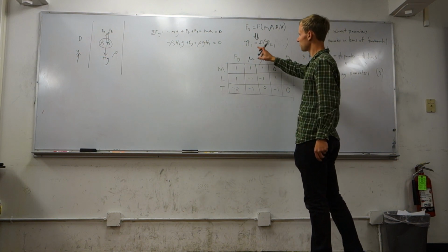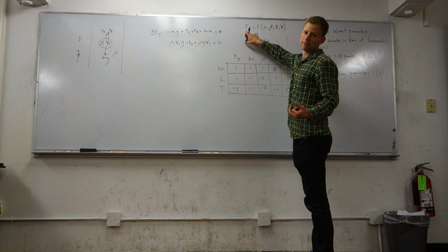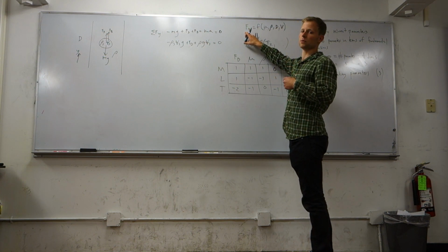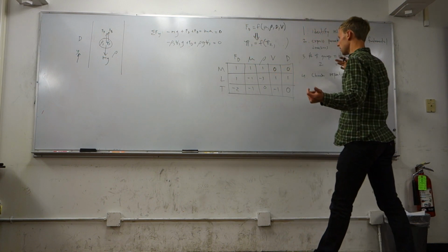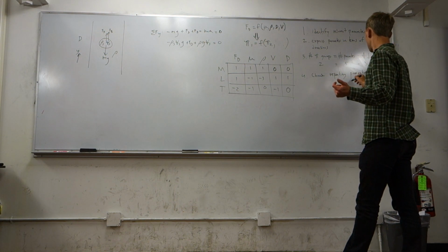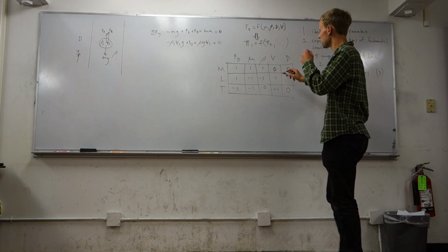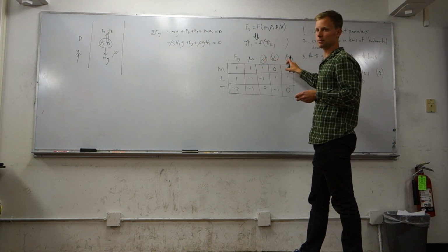And also it's nice to have the variable you're looking for not be a repeating parameter because you're going to want it raised to the exponent of 1, just so we have an explicit expression for the drag force. So I'm going to choose rho, v, and d. And then we're going to try to non-dimensionalize our other 2 variables in terms of these repeating parameters.